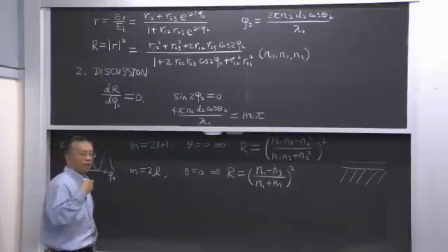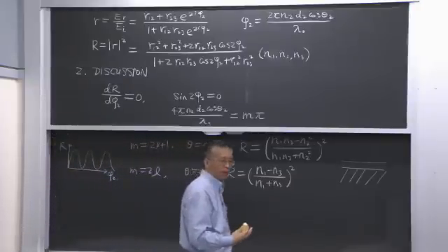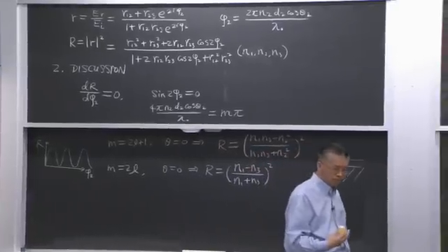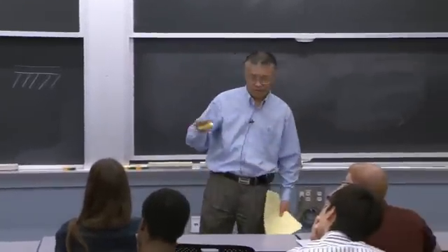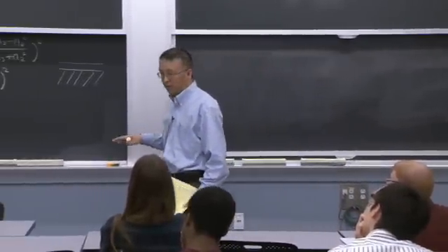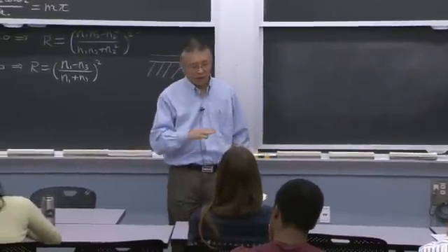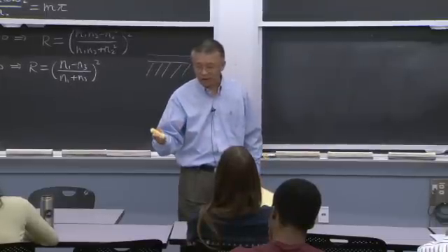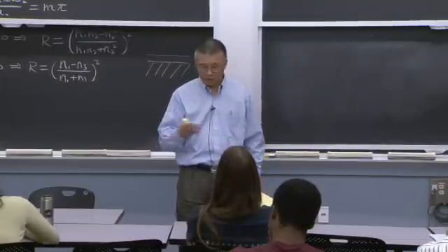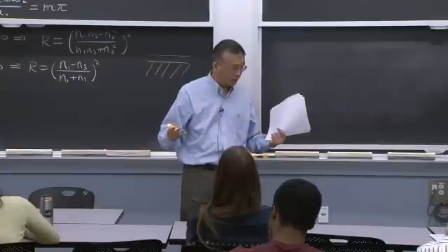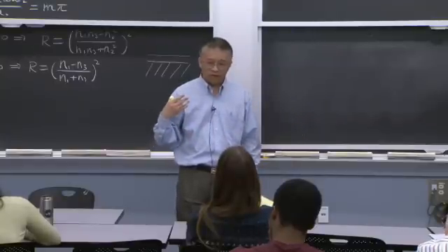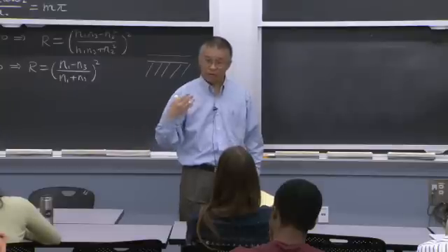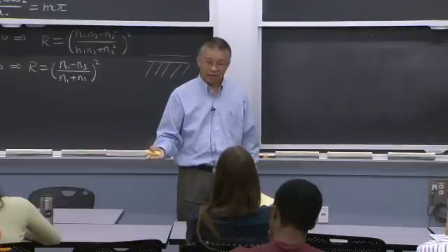That's the interference phenomena, right? If you go to the clean room, you deposit a layer of film very often. Some of you may go in the clean room and deposit a layer of film, and an experienced person will look at the color, because the white light that comes in is broadband, and because of the interference effect, some colors are reflected more, some less.